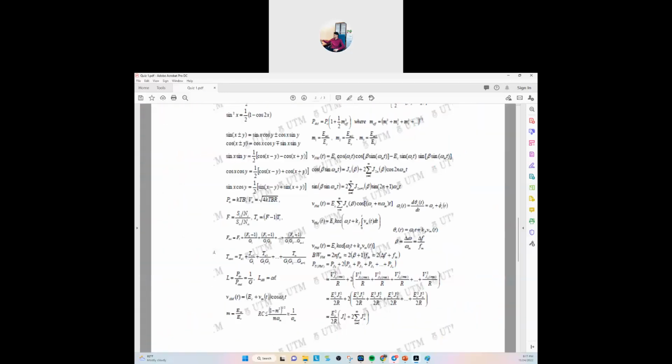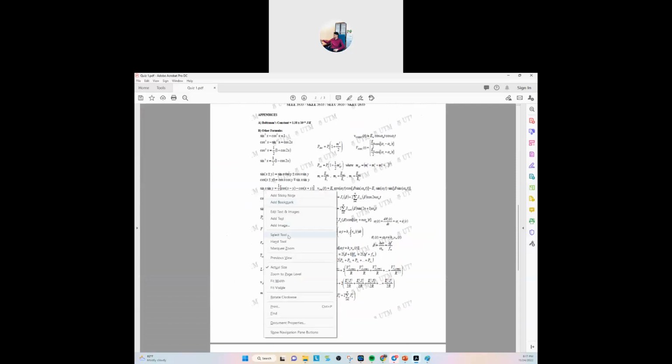So the first answer is that the first amplifier has the highest gain, big gain, big noise factor, and after that big noise factor for the second and third amplifier or subsequently, and the gain of the second and so on is smaller. That is the answer, pretty much based on the equation.